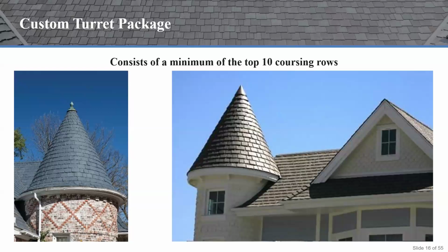Turret kits. A lot of manufacturers are now starting to offer custom turret packages. A turret on a building is a very complicated aspect of the building for a contractor to tackle. It takes a lot of work. If you don't have a lot of experience working with natural slate products or natural shake projects, it can be very overwhelming for a contractor. So what we say is just take the measurement of your rafter, take the measurement of your rafters on that circle, and then either get the diameter or the entire circumference of the circle.